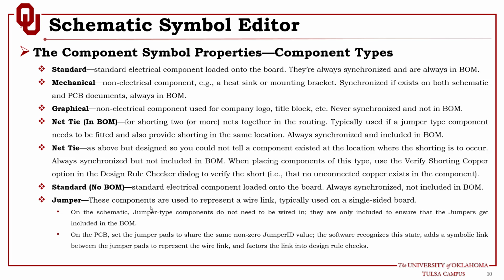So basically you can place a component in a specific configuration for a specific operation or features of the board, and we do that all the time when we do a design. So instead of doing two different designs and making two different boards, we do one, and we have a component configuration on the board where we populate some of the components and skip the others, or do it the other way around. So what is the benefit of that? It's a saving factor.